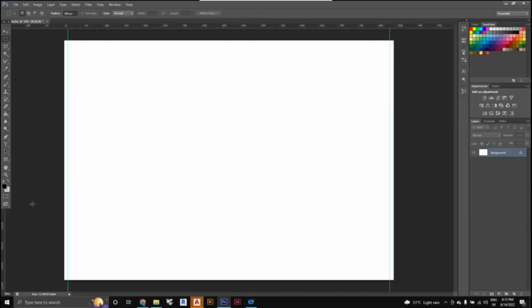There is one more method to produce a guide: you can click on the ruler and just drag it. You can see that the guide comes up. There is also some writing coming in, like 61.4 mm, being shown. So if you want an approximate guide, you can use this. For example, if I want a guide at 100 mm, just move it. You can place it at around 100, but it will only be approximate, you will not get exact. Okay, 100.9 mm, and you can place the guide.